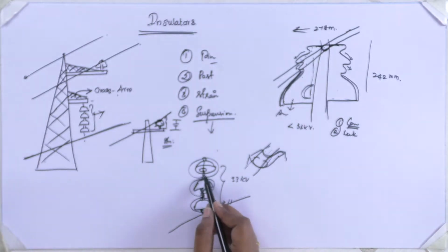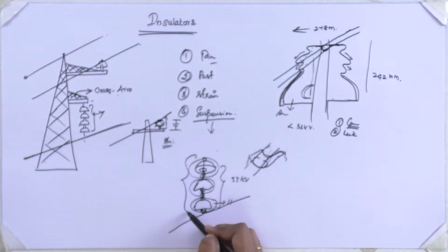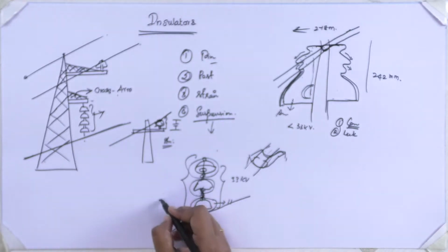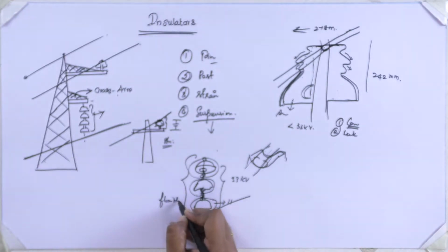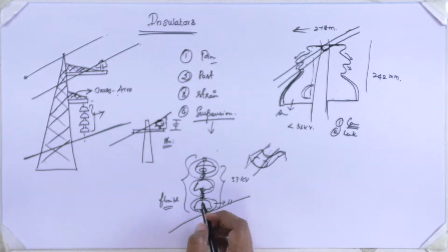By connecting with the metal clinch, the whole suspension type insulator is very flexible. Due to its flexibility, the voltage stresses will be reduced. If one of the insulators has a problem and we have to replace it, we can easily replace one insulating unit in the series of insulators. So it cannot affect the whole system.